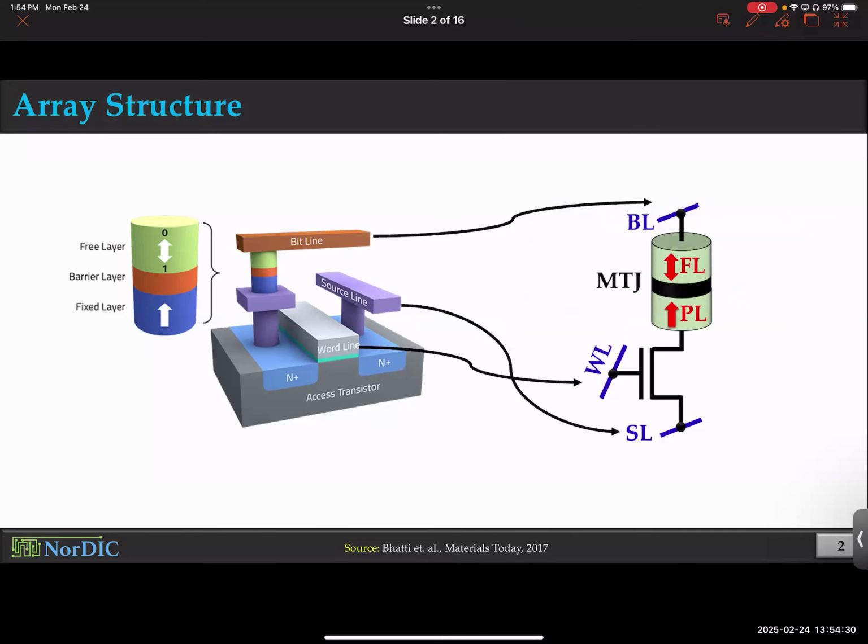But the reason I like it so much is because it shows that these layers may not be in the same metal level, and they're not, as you see. When the source line runs, it runs in a layer. Bit line could run in a different layer on top of each other. That's why they don't overlap with each other. Despite when I try to draw in 2D, it looks like they're crossing each other, but they're not. Okay, so nothing new here.